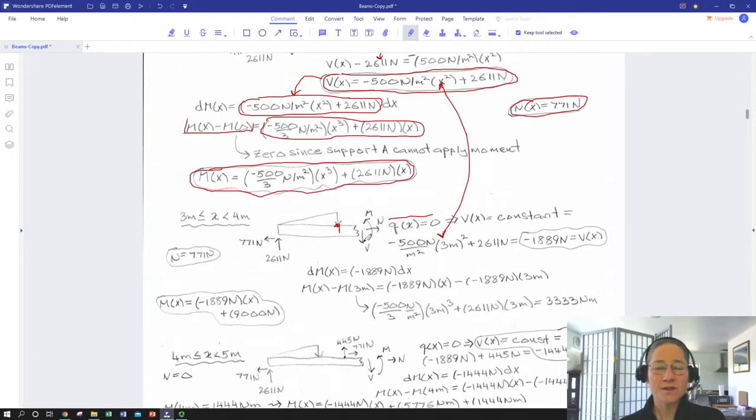So shear force, internal shear force on the right end of a cut beam, is defined as positive in the vertically downward direction. We got a negative value. That means the beam that we cut off on the right hand side is providing an upwards force along that area, or along that portion of the beam, that length of the beam.